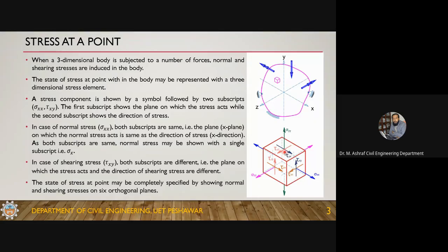Similarly, you have this y face. On this y face you have a normal component, and I will discuss this in detail with the subscripts, and 2 shear components, in the x and z directions. And on this z face you have a normal component, shear in the y direction and shear in the z direction. So on each face you possibly have 3 stress components.